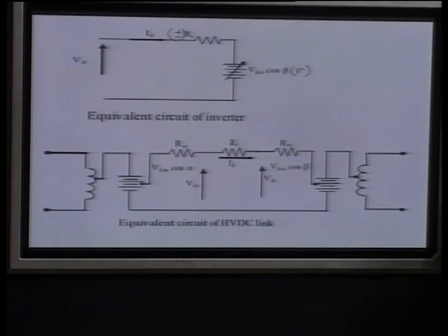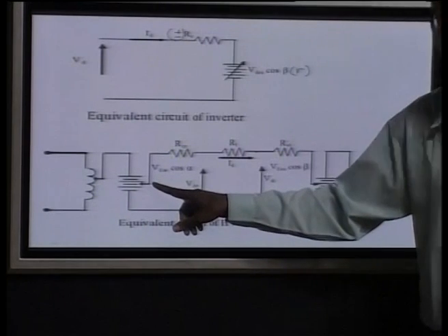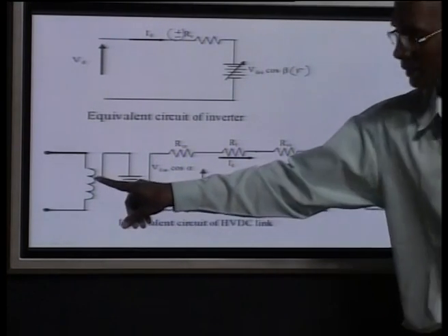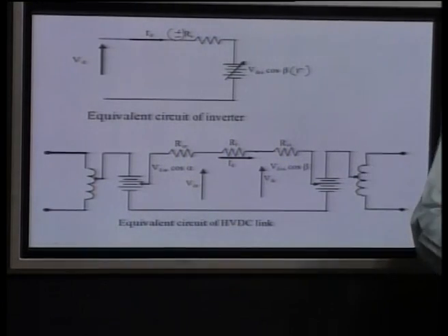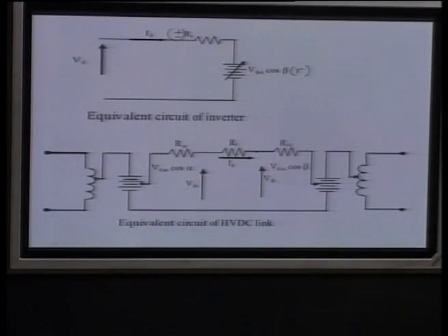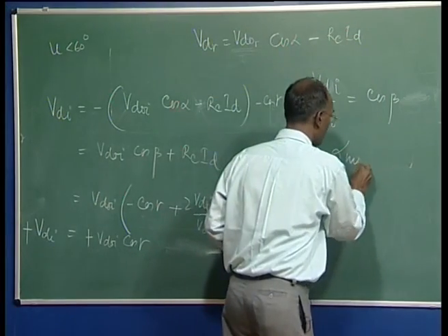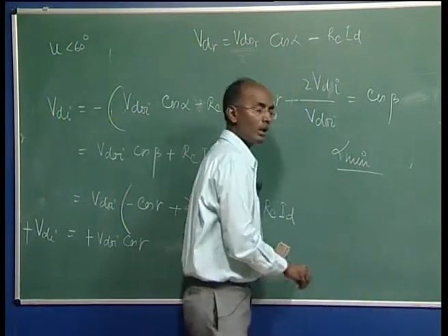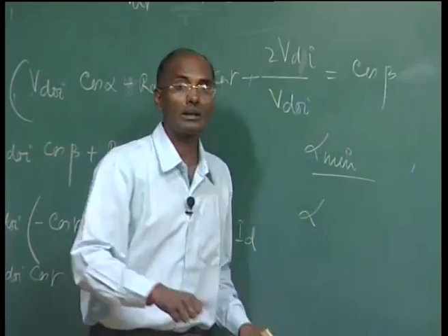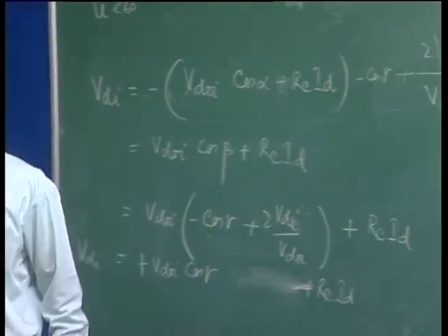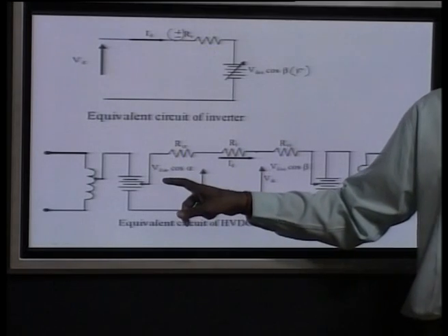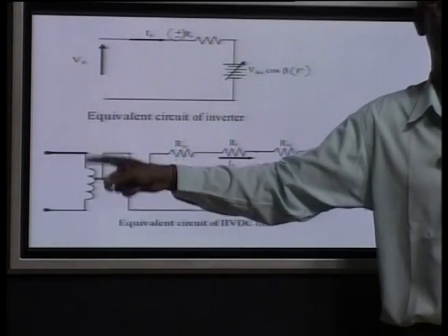But we always prefer to change this voltage, because this is very fast compared to this. First we have to exercise this alpha delay, but there is some delay limit. As I said, alpha has some minimum value, you cannot go below this, and if you go for larger alpha it deteriorates the power factor. So, it has some limit. So, in between it is controlled, and if it is hitting the limit we go for tap changing as well.